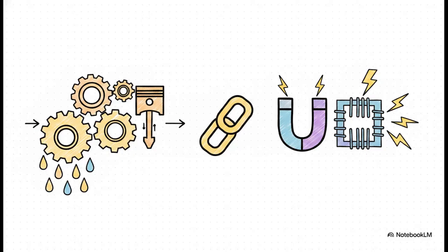Let's put these two loops side by side really quick, because this comparison absolutely locks the whole concept into place. On the left side, we have the governor loop. It controls active power by physically moving a fuel rack to manage engine speed. On the right, we have the AVR loop. It controls reactive power by electrically modulating the excitation field to manage voltage. One is basically a mechanical muscle, and the other is an electrical magnetic field. But the key here is they are operating simultaneously, side by side, every single second that ship is running to keep the power plant perfectly stable.